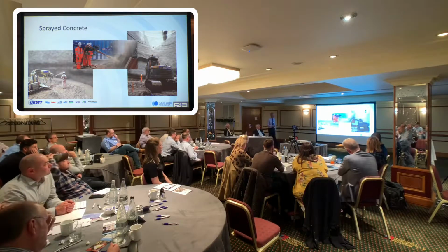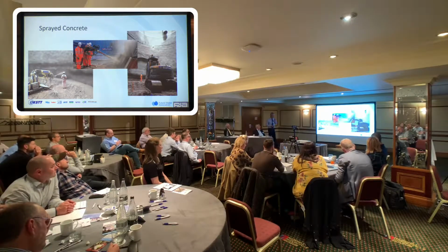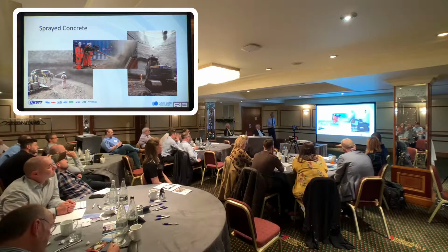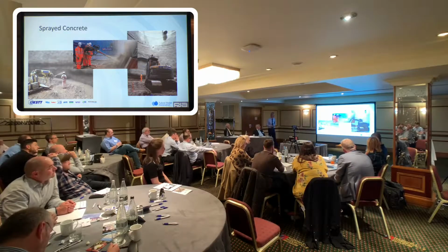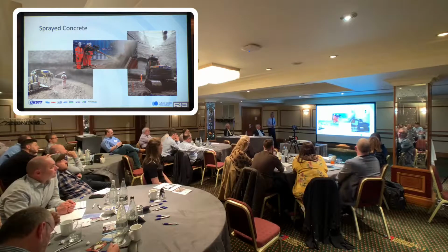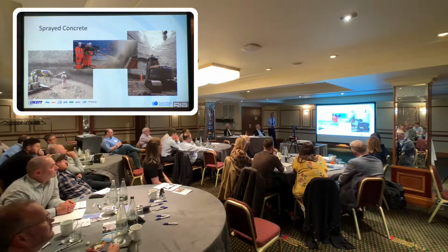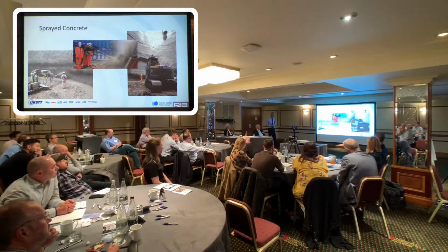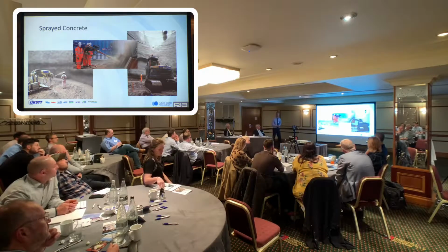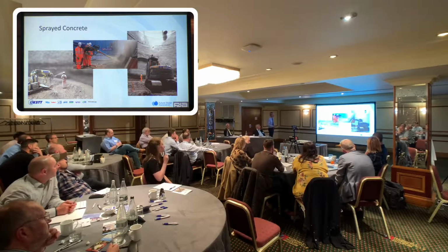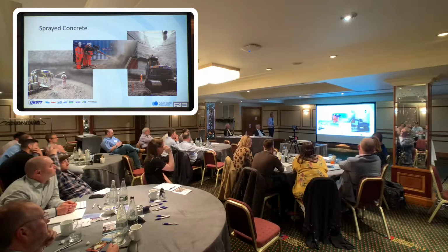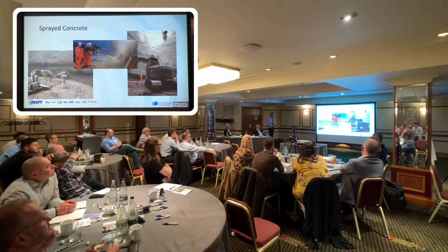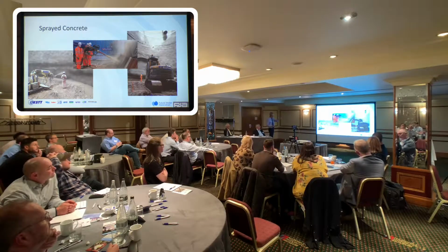It's worth talking about sprayed concrete because it's a very flexible and useful way of supporting shafts. These two pictures are the same shaft. They're on the National Grid cable tunnels project that Costain did a number of years ago. Yeah, and Mr. Dexter worked on it as well in his previous incarnation. So it's using robots to spray concrete onto, in this case, London clay.